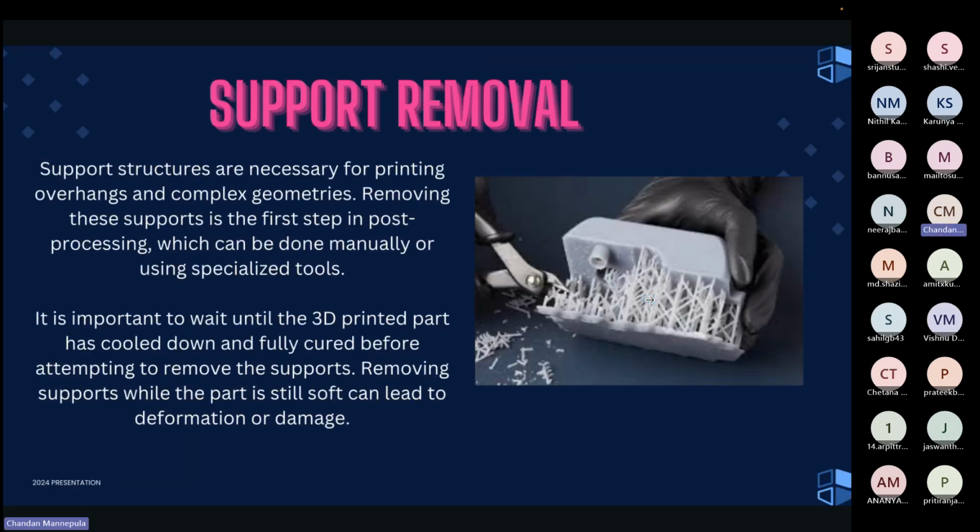While building a sphere, the contact area of the base is very small, so it won't be as stable as you think. In order to build a sphere, you need to build support parts so that it won't move from its original position, and we can get a stabilized and more precise 3D model.